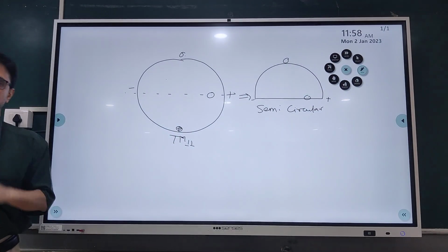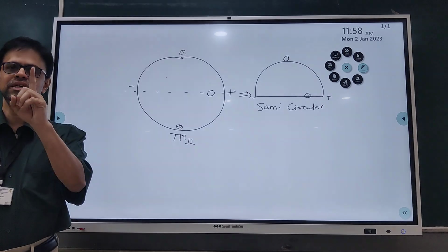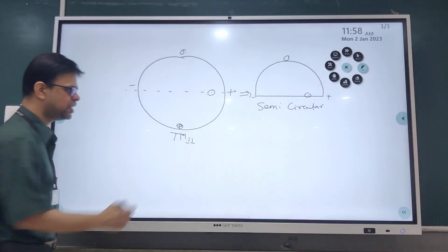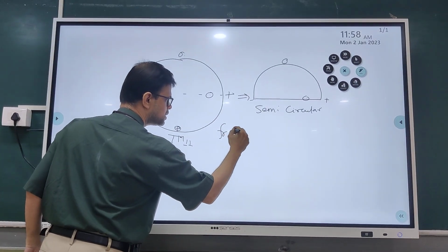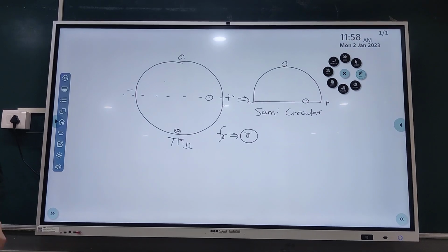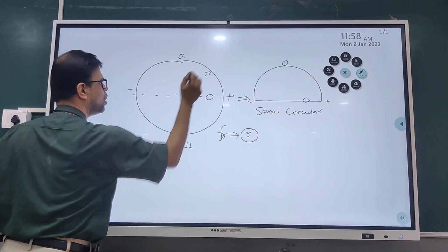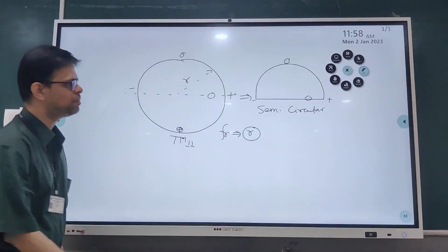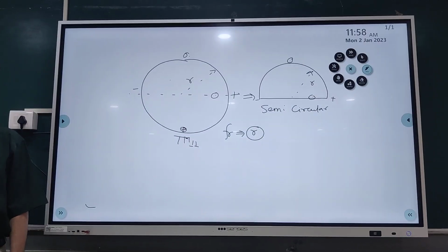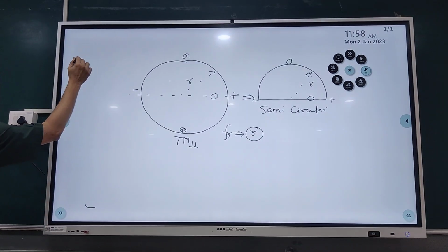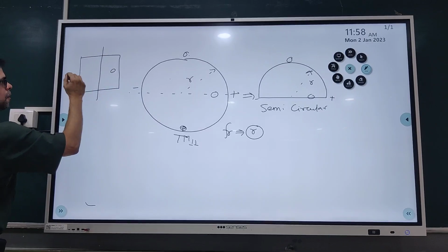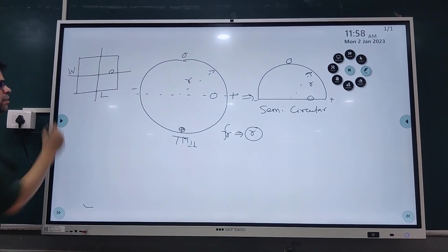microstrip antenna. Now why can I do it over here? The main reason is, in the circular design, the resonance frequency fr is proportional basically to the radius of the patch. And in this procedure, I am not at all changing the radius of the patch. Okay? Unlike this case, just consider the example of the rectangular microstrip antenna. Here, this is your length, this is your width.